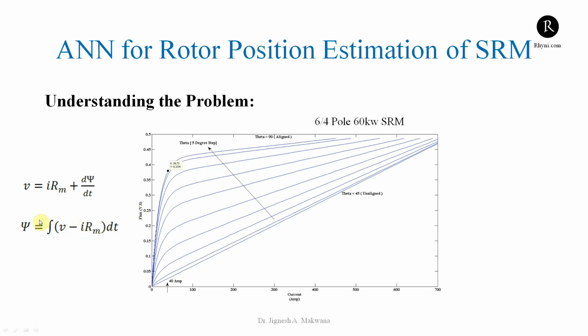So in simulation our inputs will be flux and current, while in an actual setup there will be a current sensor and a voltage sensor. When we eliminate the position sensor, we need a current sensor and a voltage sensor, which are lower in cost and size.